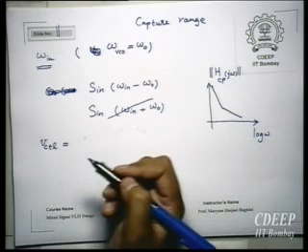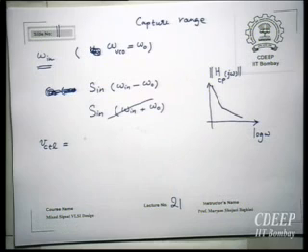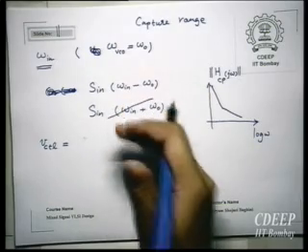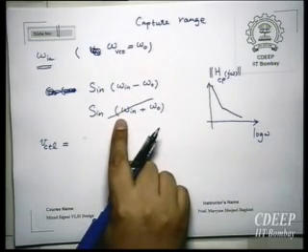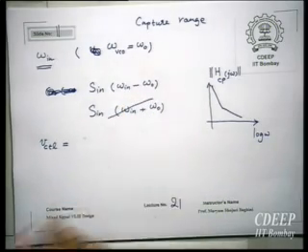Yes? What is the question? This is a multiplier. I assumed I have a multiplier. The phase frequency detector is almost a multiplier. Effectively, it generates these harmonics. Even it can generate, like, 2 omega in plus omega 0 and this. So this is just a simple assumption.